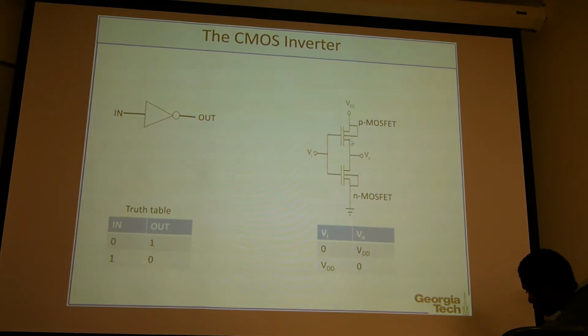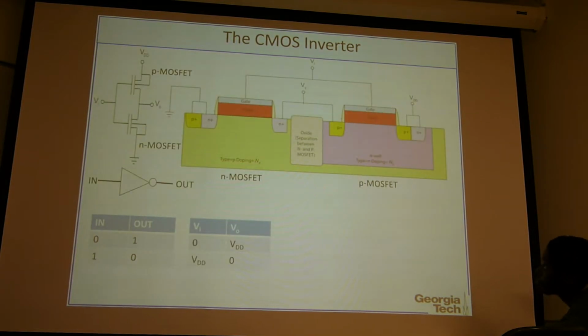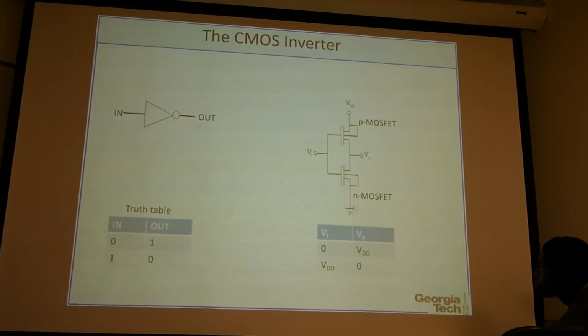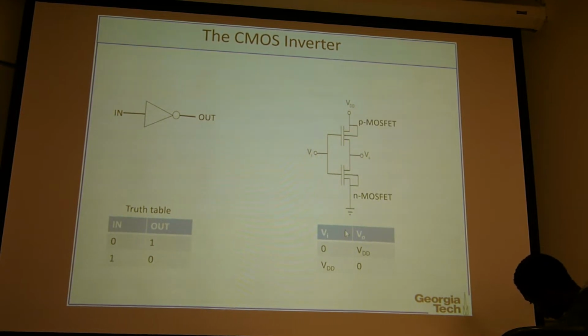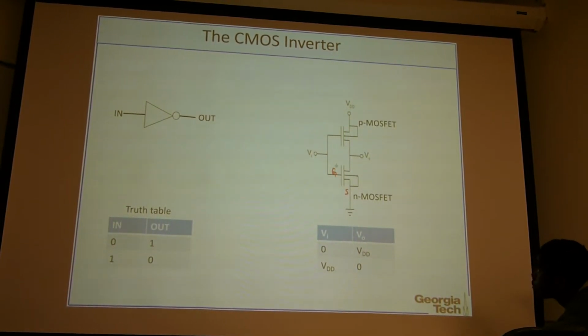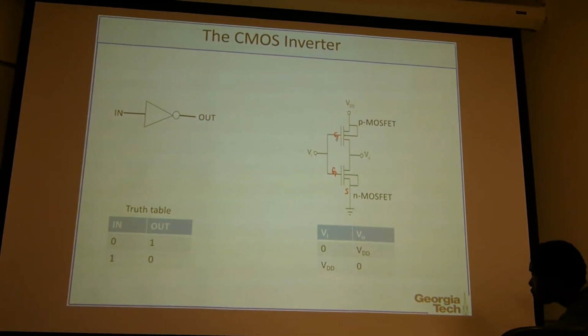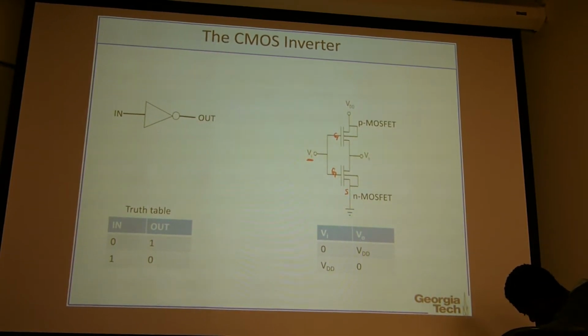What is real on the chip is those 2 transistors, one NMOS, one PMOS. And then they have this kind of connection. So the NMOS source is ground. So this is the source of NMOS. NMOS gate and then PMOS gate are connected together as the input voltage Vin, or this Vi.